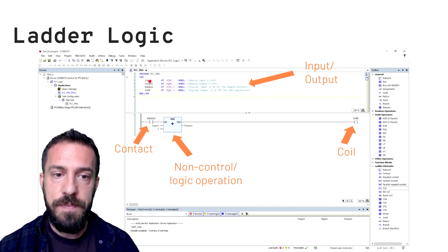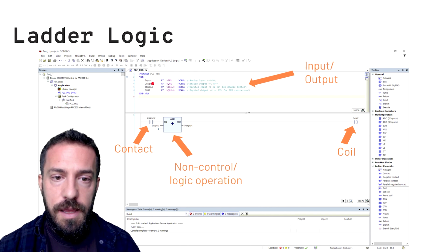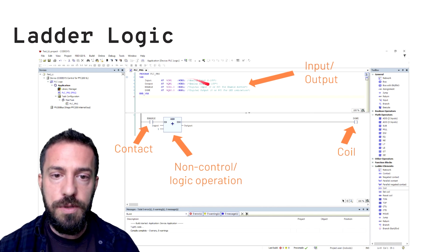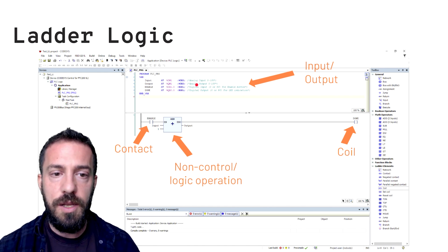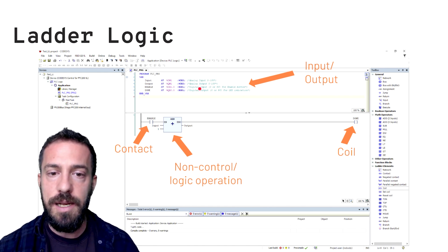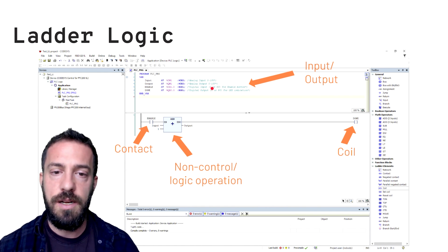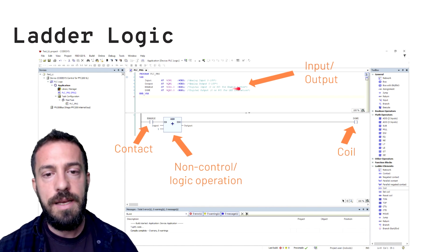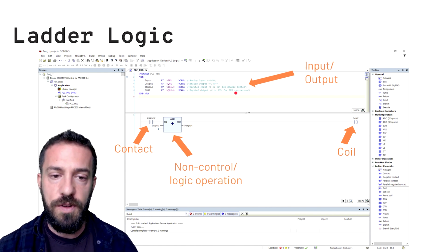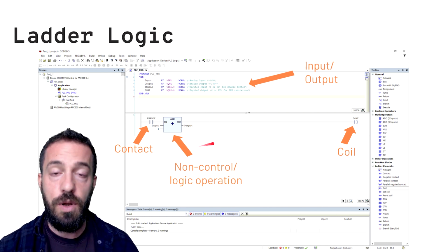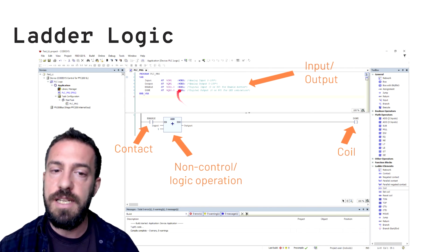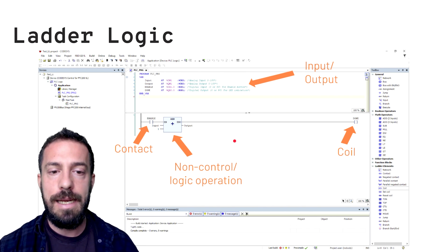You can see the three inputs, two analog inputs, 0 to 10 volts, and an analog output. Enable is a digital input, so 0 or 1, 0 or 5 volts, with 5 volts for 1, for the enable button, and the output for the LED indication. So this is how ladder logic would look, how you would program a very simple program we have here in ladder logic.